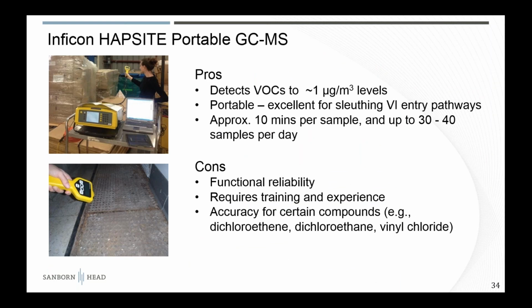On the downside, depending on who you get this from, it has some issues with functional reliability. And it requires some special training experience. It's not as simple as using a PID. The instrument needs to be calibrated. It should be checked daily. It's calibration checks on a daily basis, which means you have to have a standard gas available that you can check the readings against.